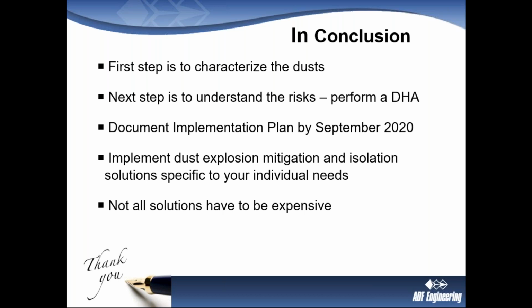How should it be collected? You want to try to get as best a representative sample as you can. That is, collect a large amount of material from a dust collector, ideally, and then sample from that larger collection. Okay. With something like a sample thief. That would be ideal, if that's feasible.